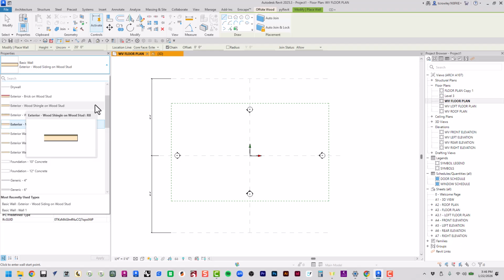There are waterproofing elements to, probably not these walls, but to our exterior walls. And then there's a finish on either side of the wall. And this wall behind me actually has some concrete masonry unit on the other side and some split face, right? So if I were to think of one of these interior walls as a composition of layers assembled as one wall, it would be drywall, 2x4 stud, and drywall.